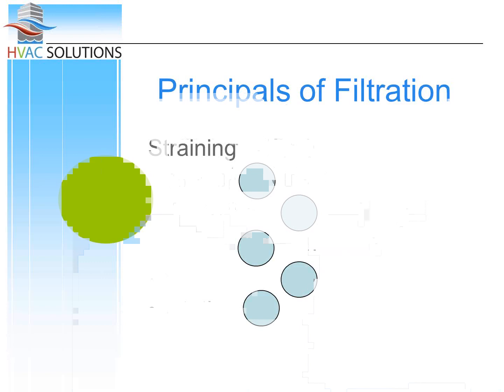So, principles of filtration. There are 4 principles of filtration, and to be a HEPA filter, you have to utilize all 4. I'm going to actually talk about 5 because there's a new one that is not actually a principle, but it makes the other 4 more effective. So the first one is straining. And straining is actually the easiest to explain.